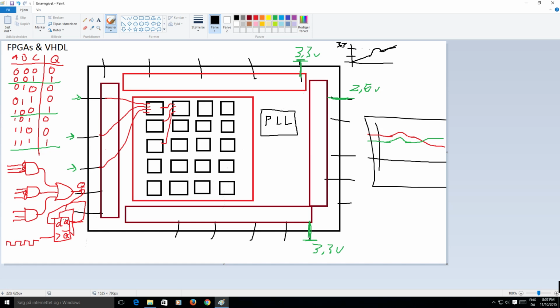You can set up a chain of flip-flops and then run them synchronously with the clock. And you can get your half output, a quarter, 1/8, 1/16, and so on. And that will only give you the propagation delay of 1 of the flip-flops. But if you start adding gates to these signals and you feed that to another chain of flip-flops and so on to get your desired frequency, then your final clock output will be shifted in phase compared to the main clock. And you don't really want that inside an FPGA, because if you do that a lot, you might end up having more than one clock period of propagation delay, and then nothing will work.